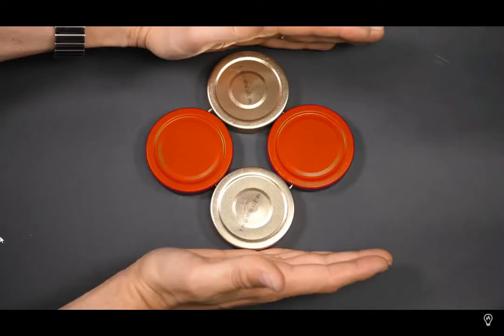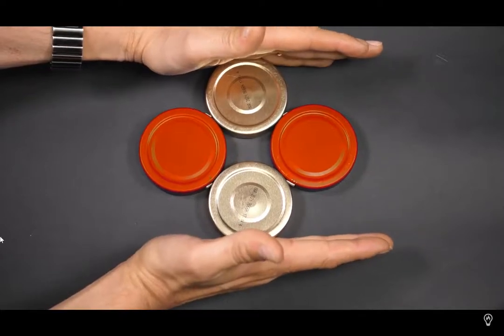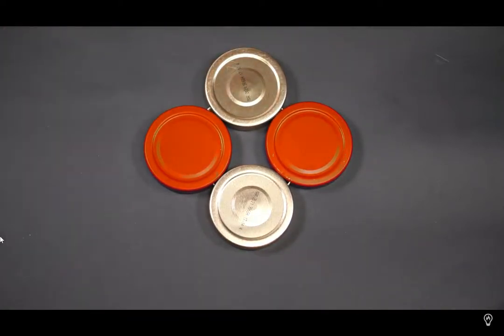To see why a lack of point symmetry is important, look at this arrangement of atoms that does have point symmetry. See how silicon atoms are opposite silicon atoms, oxygen atoms are opposite oxygen atoms. When you compress the crystal, you move the charges symmetrically, so the average position of those charges doesn't change, it stays in the middle. The piezoelectric effect has a lot of uses besides just a high voltage power source like in a barbecue lighter. It can also be used as a sensor.